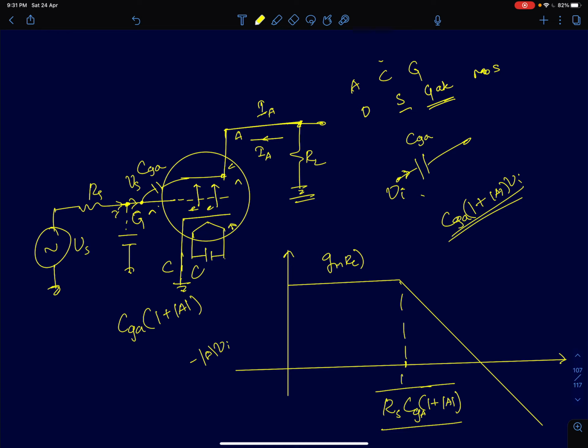So I'll roughly look at what happened, how engineers chanced upon this cascode amplifier structure when they were trying to fix the problem of low bandwidth in vacuum tube amplifiers. Shown here is a 3-terminal vacuum tube amplifier. The 3 terminals are anode, cathode and the grid terminal. They are equivalent to the drain, source and gate terminals of your MOS device.